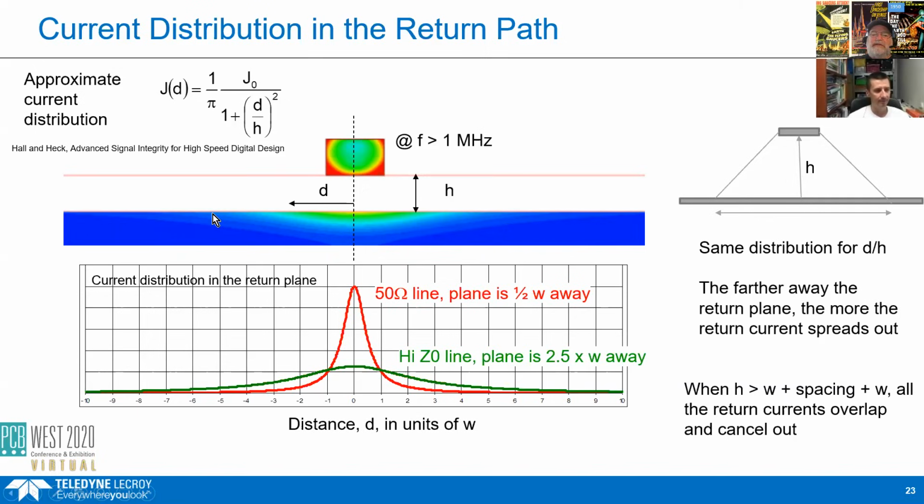And as long as the return path is wide enough to accommodate that return current, then it looks like an infinite plane. I could literally cut out this copper over here and this copper over here, not affect the signal quality or the impedance the return current sees. It means that when you need to route two tracks parallel, and if you go beyond the green area, then you will be absolutely safe, and the tracks will not influence each other?